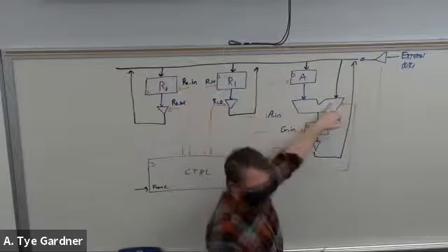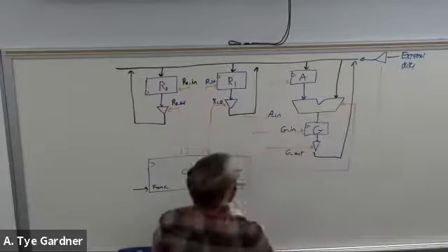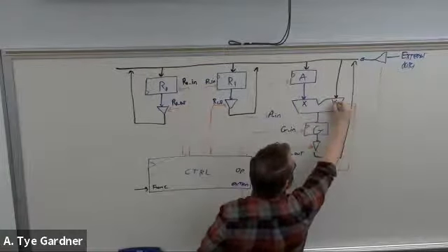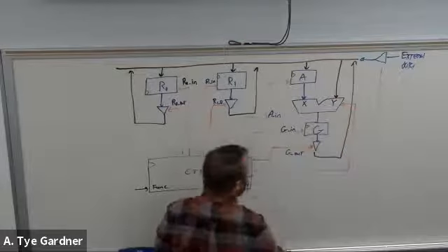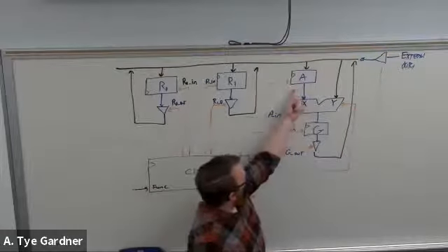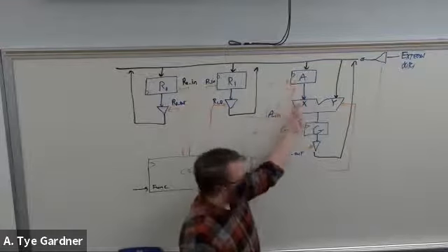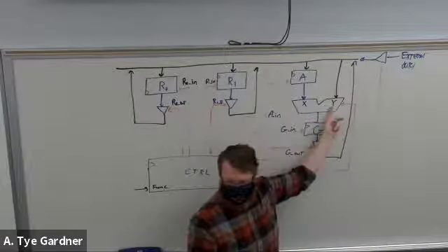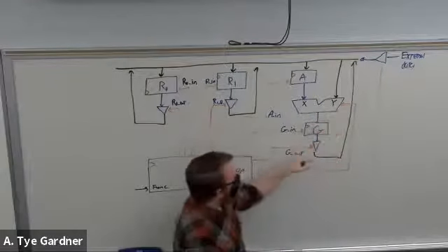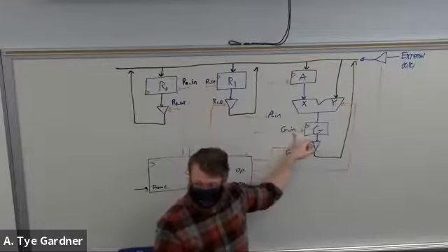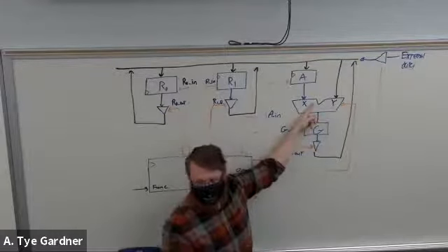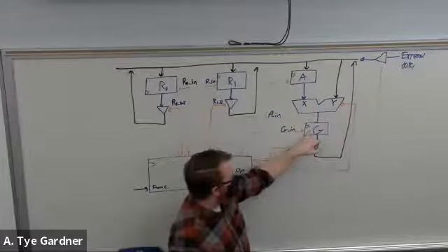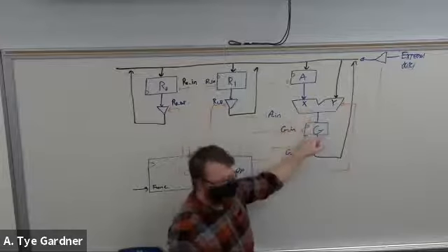Send a signal around to the B port. I should probably label that. Actually, let's call it X and Y since we have an A already. So 3 is in this A and is appearing at the X. 7 is on the bus and appearing at the Y. So all I need to do is on the next clock cycle, enable G in, right? Because this is combinational logic, it just happens as fast as it can. So then the clock cycle G in says, let's save X and Y. So G gets a 10 on it.